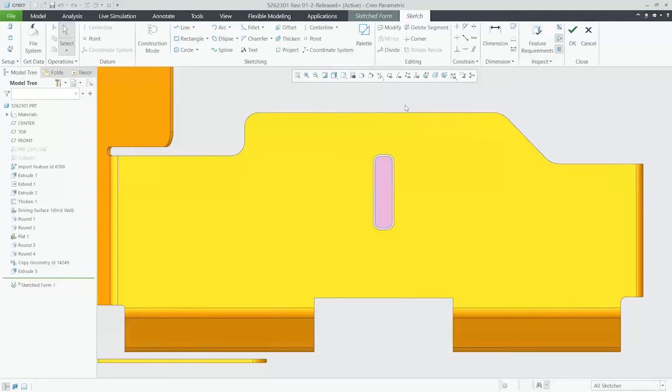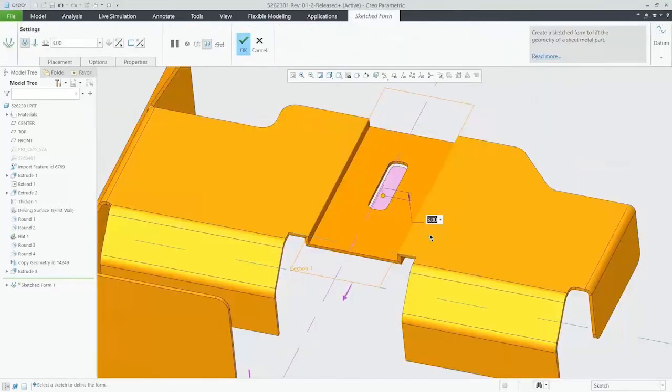Here we can reference the back. And then create maybe a cut from here to create our punched form. So this is going to be the sketch that we'll use to create that punch. Again, this is just regular Creo work, just a little example of sheet metal and Creo. We need to make some changes here so that we can look at updates.